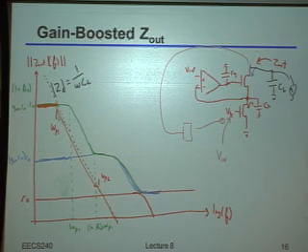So what I'm basically saying is that if I built this whole thing and I tried to design the GM of that amplifier such that I could actually take this and move it out, for example, over here somewhere, meaning that's the gain bandwidth I was wanting, now this is going to be a big problem, right? Whereas if I was only looking around over here somewhere, that pole-zero doublet would be outside of the frequency range I care about. So that's really the most important point: once you start getting into this gain boosting stuff, if you really want to make sure it works the way you intended, you better make sure that that pole-zero doublet is outside of the frequency range you're interested in for your overall response. Because if it's not, it's going to show up and cause some other thing that potentially could dominate your overall errors.